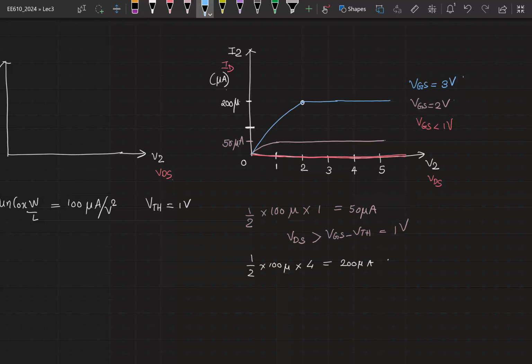a line like this. Quickly calculate for VGS equal to 4 volt. This is 450 microamperes. So this is 300 micro, 4. My 450 microamperes is somewhere here. And you'll see that the value is valid from 3 volt onwards. So I wanted to show you how the curves are going to get spaced. Even when your VGS is increasing by equal increments, your curves are not at equal spacing, right? And that is because you have a quadratic relationship.